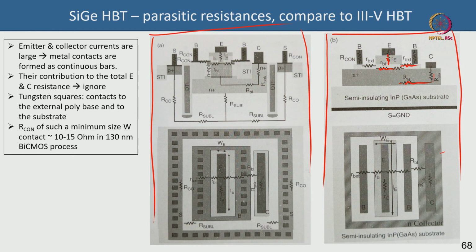As I told you, silicon germanium is actually grown. You have p-type silicon from the side. Okay. Actually, this typical silicon germanium that you are looking at is called double polysilicon, because you have polysilicon on this side and polysilicon on this side on which you contact the base, and this polysilicon contacts the intrinsic silicon germanium base here, right. So this is called double polysilicon self aligned. This is a self aligned process again.